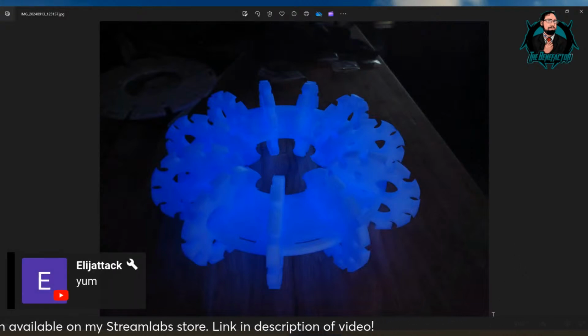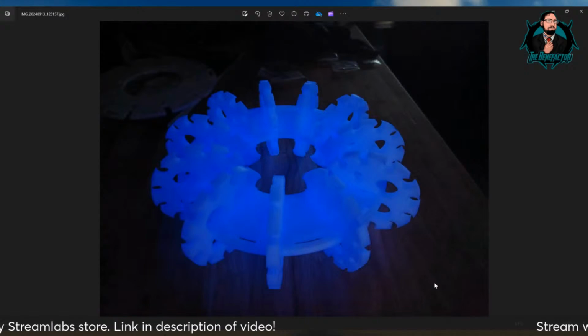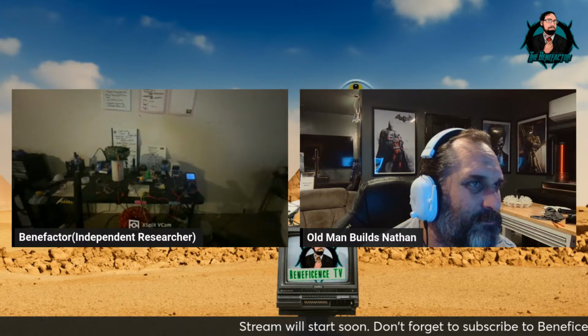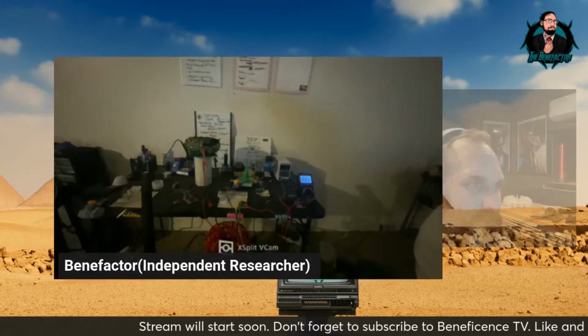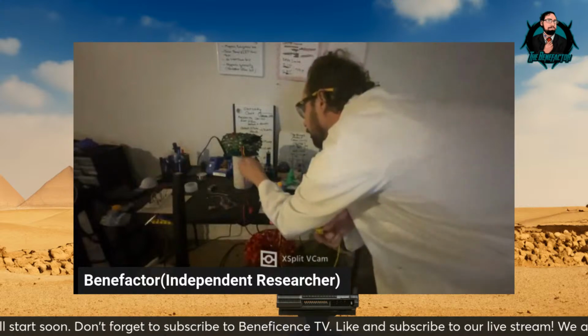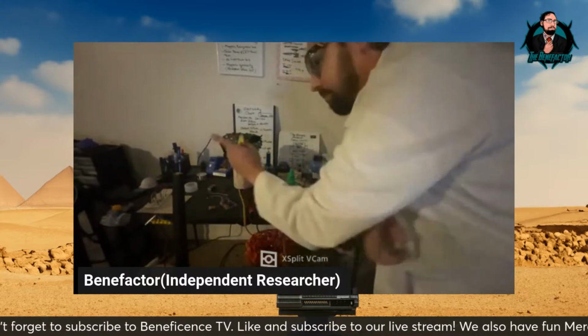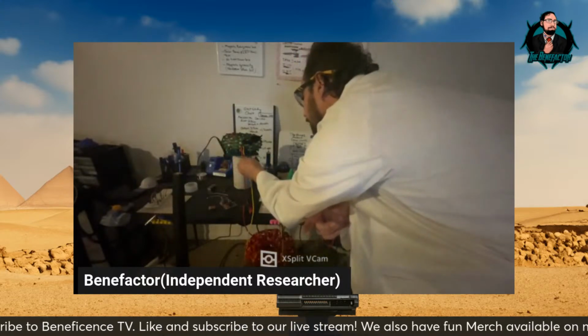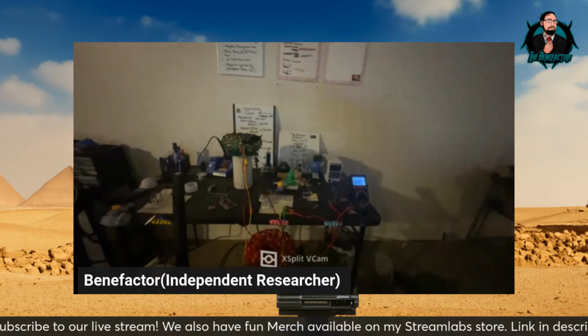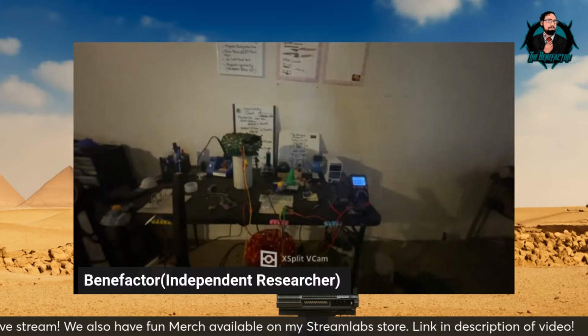So as you can see, even though I don't have the power connected, I like to get in the habit of using the one hand rule, where I either put one hand in my pocket or underneath my armpit. This just mitigates the accidents that happen.